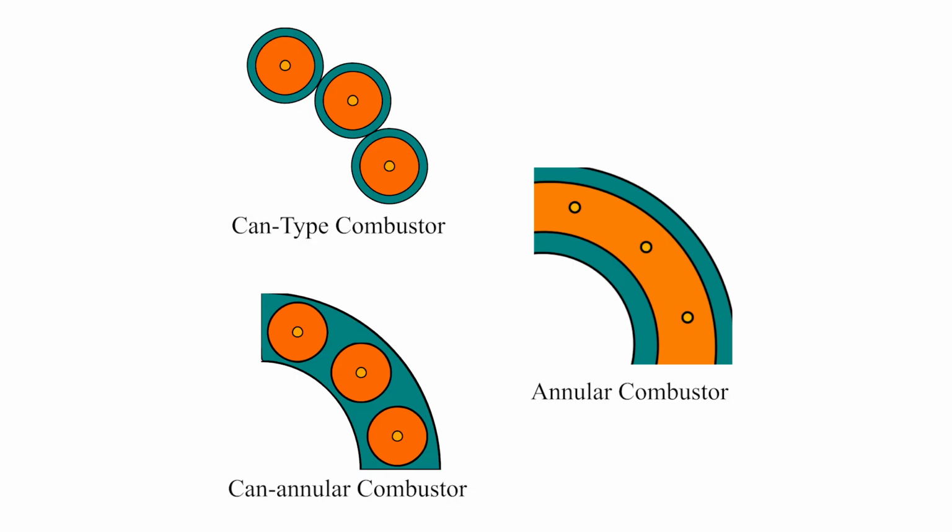Next, let's learn about afterburners. An afterburner, or reheat, is an additional component added to some jet engines, primarily those on military supersonic aircraft. Its purpose is to provide a temporary increase in thrust, both for supersonic flight and for takeoff, as the high wing loading typical of supersonic aircraft designs means that takeoff speed is very high. On military aircraft, the extra thrust is also useful for combat situations.